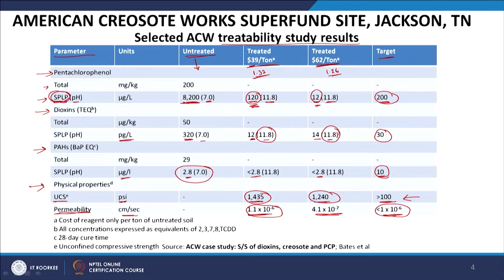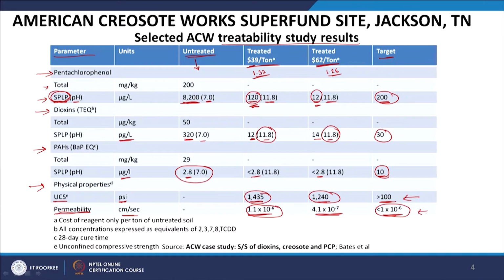Again, why do we want the permeability to be less? The reason is that if you have this particular matrix surrounded by the relevant soil or such, and you have water coming down, here they were looking at acid rain, but let us just think of rain. If the rain penetrated the soil cap and so on, and your permeability is low, it will flow around this particular mixture rather than through the mixture, right. That is obviously one of the reasons why they look at trying to minimize the permeability though, right. So again, that is something to keep in mind.